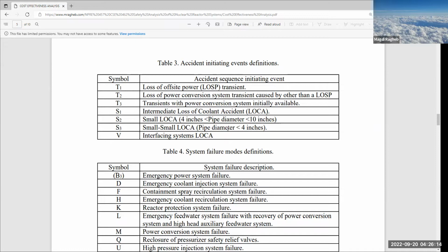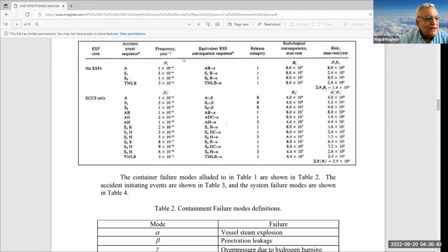In the 3 Mile Island accident, that valve stem opened up and did not reseat itself, even though there was a light here at the operator stand that told him, oh, well, it's lighted, so this means that that stem is operational, but it was not operational. So in that case, it was a small break loss of coolant accident for the 3 Mile Island accident in general.